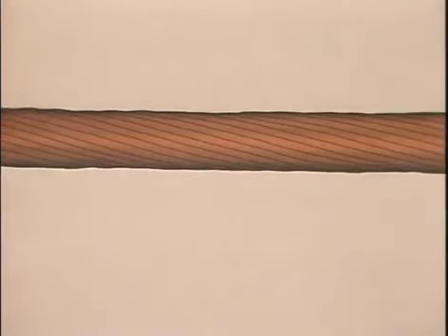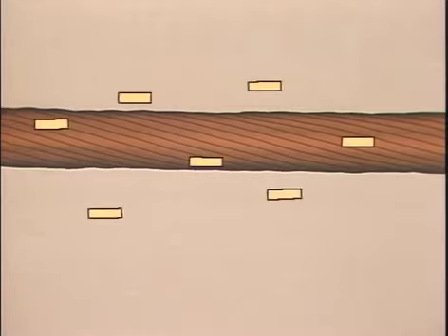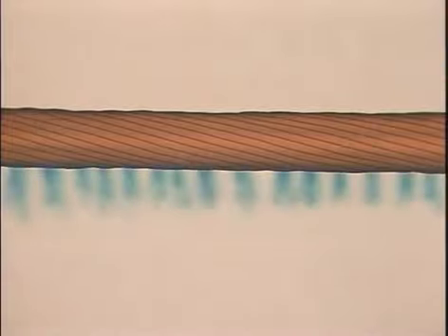Another effect that contributes to power loss is called corona. Corona is the ionization of air surrounding a conductor at high potential, in which power is lost directly to the atmosphere. Corona results in an electrostatic field surrounding the conductor that creates power loss in the form of high voltage impulses, radio frequency interference, or RFI, television interference, or TVI, and audible noise. Under certain conditions, this field is visible as a blue glow.